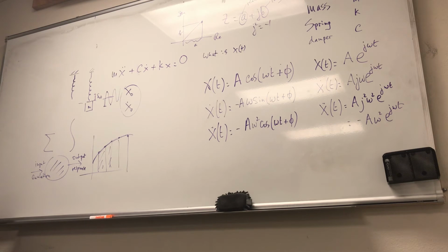But if you want it to be closer to reality, then really the rider and the motorcycle are not moving exactly the same. Maybe occasionally he may bounce. So you need to remove the mass of the rider and then put in a spring and a damper. You see how the models start?